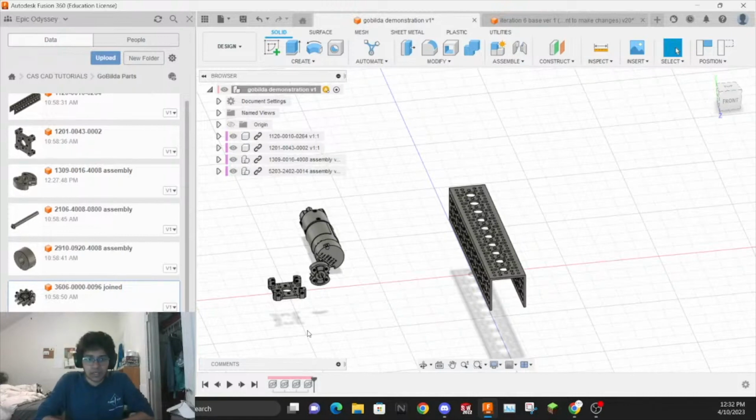Sorry. And you could also use a bunch of other wacky stuff. You could use swerve drive, which is done by barely anyone in FTC. I don't recommend it because it's really hard to do. Like only Gluten Free has made a really successful one that most people copy. Swerve drive uses two differential cores.